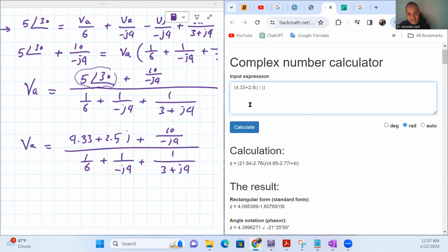So in our circuit analysis, for the complex number, square root of -1, we use the symbol J. But in general, in math, we use the symbol I. And why don't we use I in our circuit analysis with complex numbers? Because we usually call the current I. That's why we use J, to differentiate, not to confuse us. So in all other fields, when you use the complex number, which is square root of -1, we use the letter I. But in circuit analysis, we use J. Why? Not to confuse it with the current.